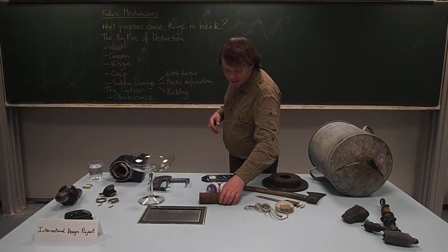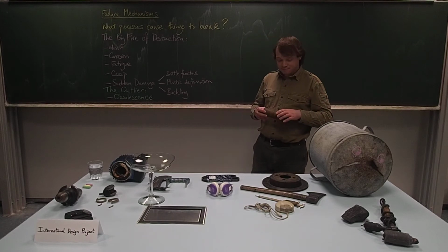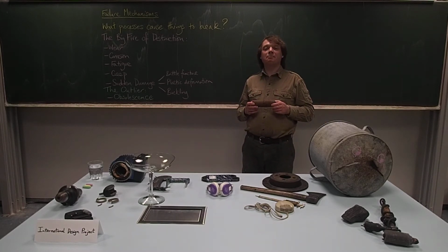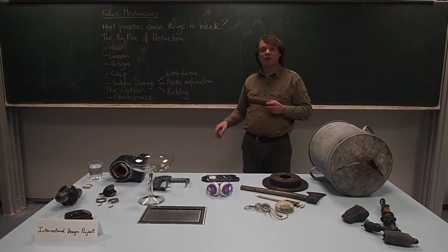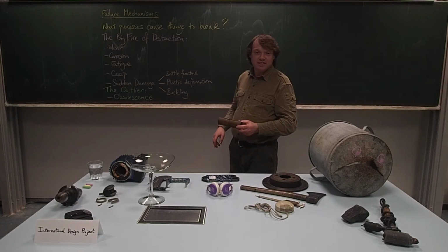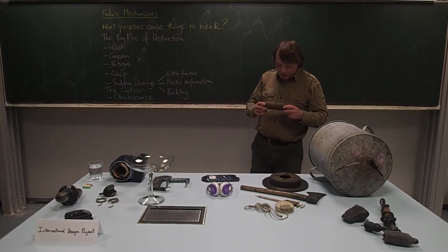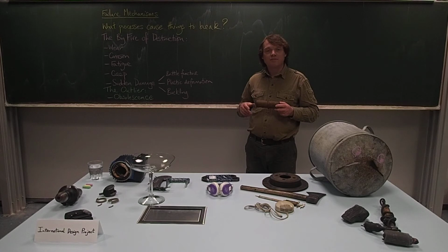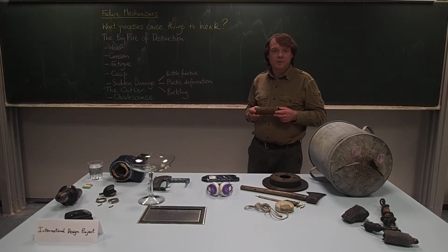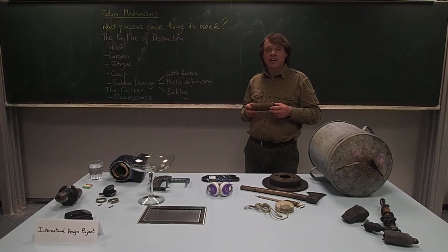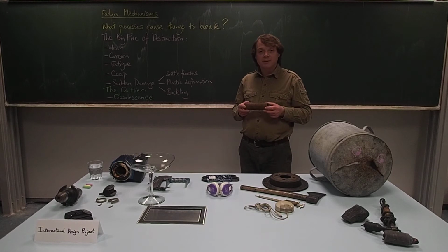The next failure mechanism I'll look at is fatigue. Now, fatigue means that a component is subject to a cyclic load, and this cyclic load, in the worst case, goes right the way through zero. So you've got half a positive cycle, half a negative cycle of stress, and over time, if these peaks and troughs are large enough, then they can cause cracks to form and grow. And with some materials, there's a limit below which this won't happen, the fatigue limit or endurance limit, and with other materials under a cyclic load, it will always happen over time.